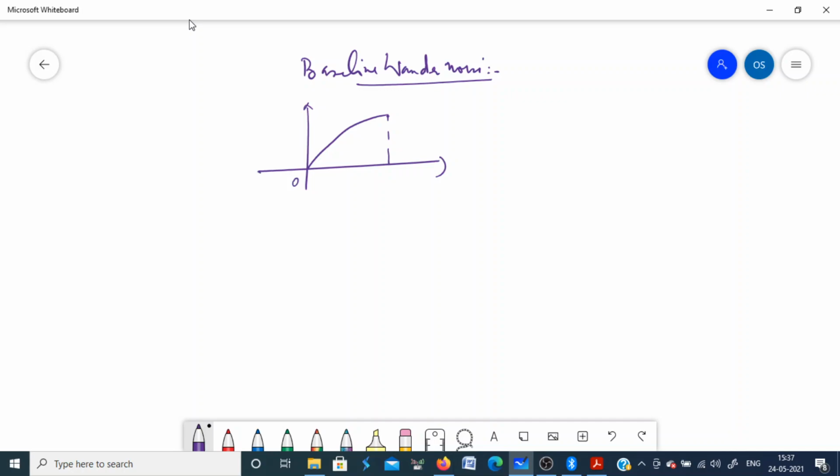Okay, we discussed in the previous class how to eliminate baseline wander noise from ECG signal. So we used a very basic operator, which was the first order difference, and which resulted in a frequency response like this, 0 to fs by 2.